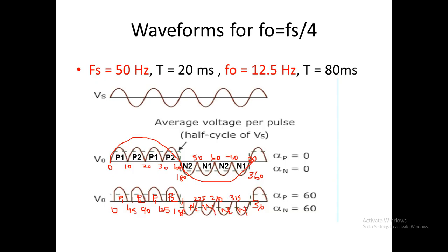So it will be 4 switching points for each resistor. So P1 will conduct twice, that is 0 to 45 degrees, and 90 to 135 degrees. And again P2 will be conducting twice in the first half cycle, that is P2 45 to 90 and 135 to 180.